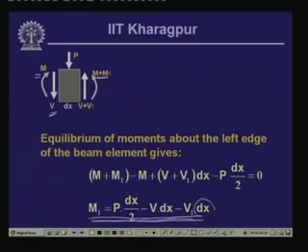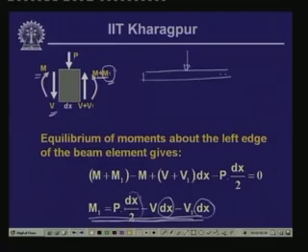Since the quantities are multiplied with this small value dx, the value of M1 is significantly small in comparison to M. Hence, at a location in a beam where there is a concentrated load, if we evaluate the bending moment on the left and on the right of the load, we find the change is very insignificant and can be neglected. So at the point of the concentrated load, the variation of the bending moment between the left side and the right side of the load is absolutely small and can be neglected.